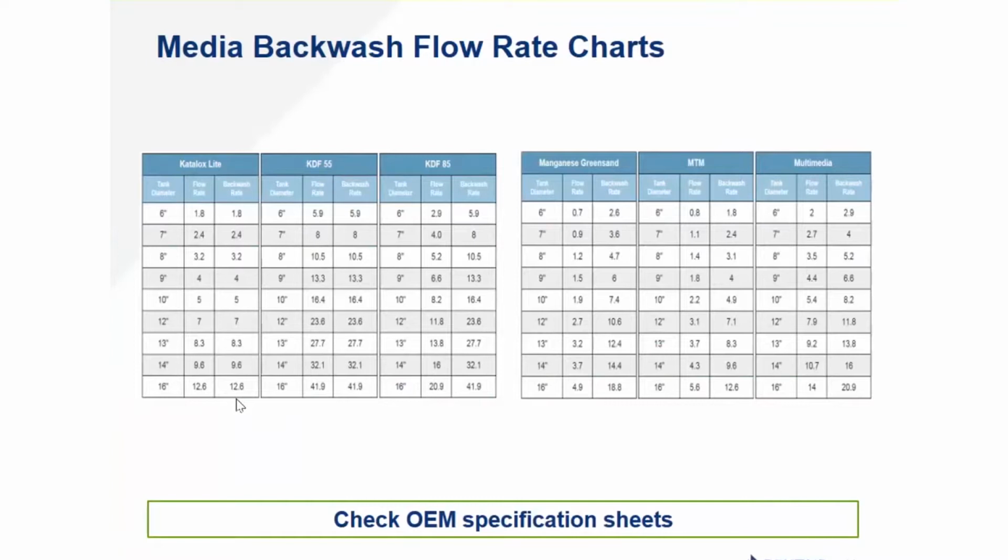Now, if we're dealing with 3900s and 2900 installs where the valve may not have the backwash rate, if you remember correctly, we've got to get that bed lift, and it's something that's going to be harder to get the larger the tank is with flow rate. So larger installations are going to have more problems with heavier medias with the 2900s and the 3900s.